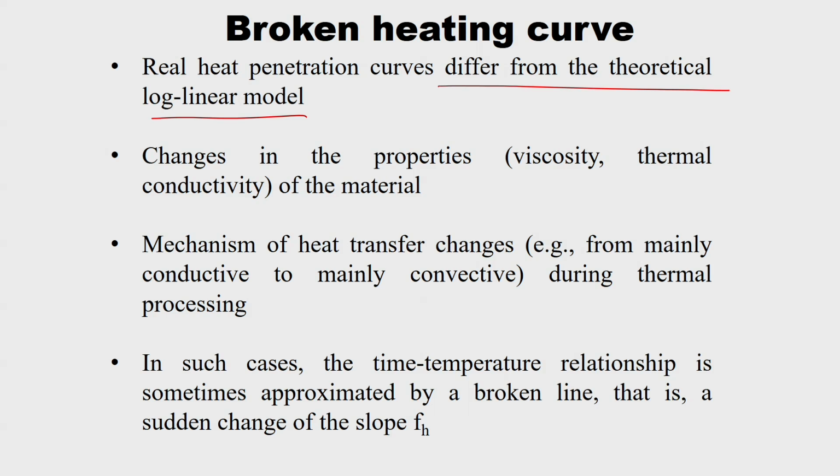So, what are the reasons? One is the change in properties, viscosity, thermal conductivity of the material. Another one is the mechanism of heat transfer, right? We told one example: in the packaging, I have a liquid medium and in that I have food chunks. So, here heat has to transfer by convection from the inside of the package material, then when it sees the solid food particle it becomes conduction. So, with this convection to conduction transition, I will not be having any information for the time temperature data.